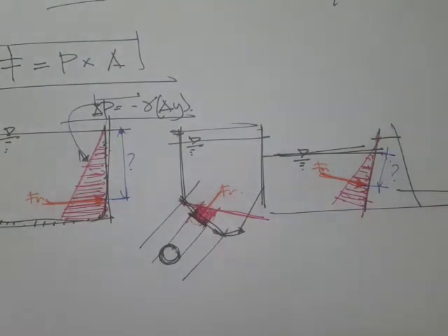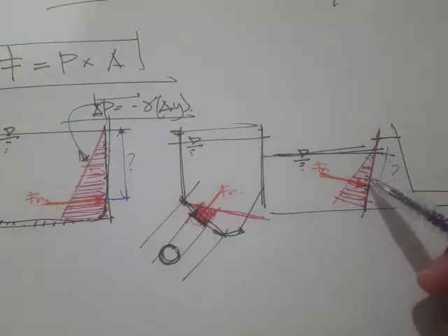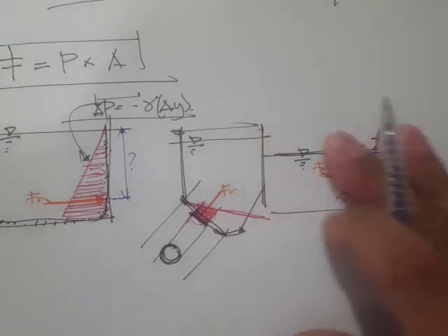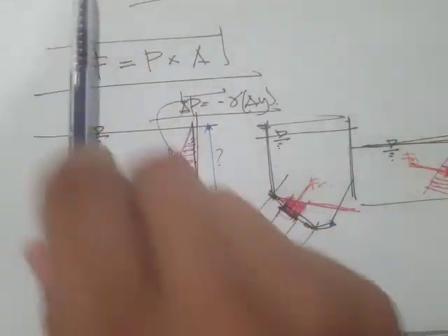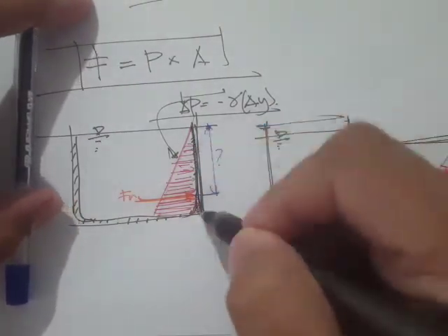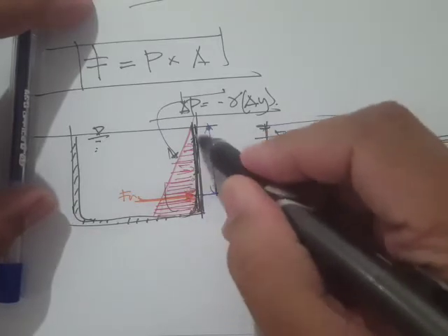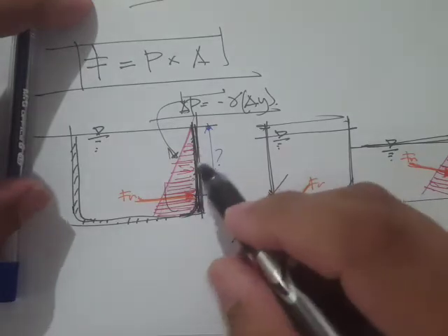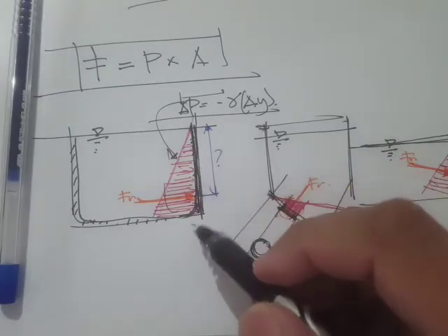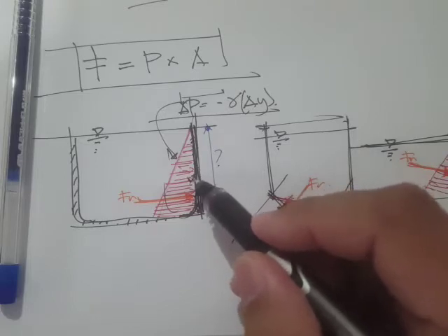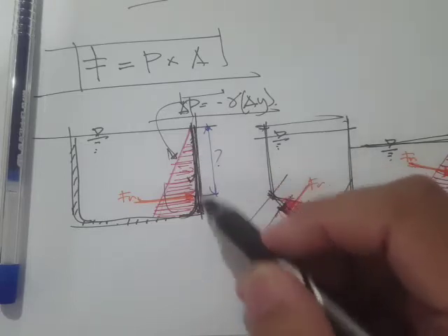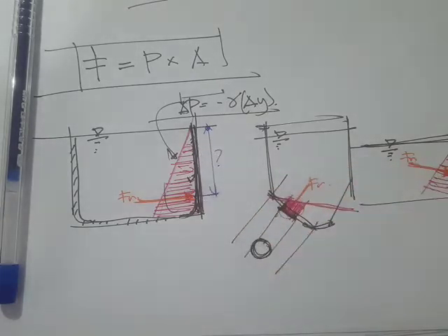So the question now is, why do we want to solve for the forces? If you have studied strength of materials already, we want to determine the forces acting on the material. So this one is an external force with respect to this material. We want to know the external force acting on the material so that we can properly size the thickness of, let's say, this storage vessel.